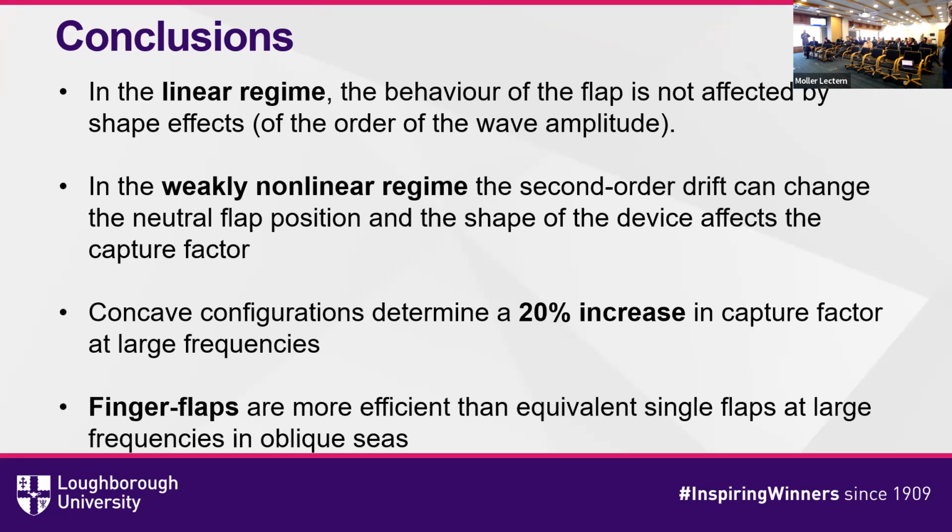So this secondary resonance is not important there, but if you move to smaller basins, it is. We've done this study with an Italian company that are trying to develop this for the Adriatic Sea, where you have 3-4 second waves. In that case, it becomes important. In the Adriatic or Mediterranean, you will not capture the first resonance at 12 seconds because you don't have any energy there.